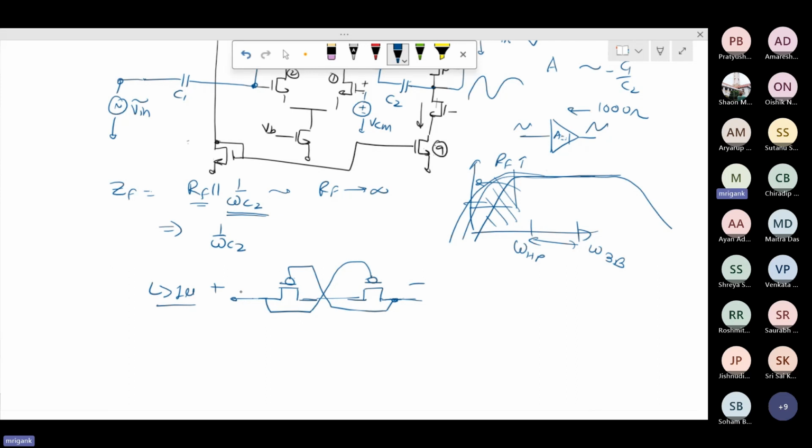And the thing is that on one side, suppose you're having virtual ground because the resistor on one side is connected to virtual ground. So suppose this is fixed DC, VDC. Suppose it is this particular node, and on the other side you are getting signal because it's a gain amplified signal. So on this side you will get signal, and on the other side it will be DC.